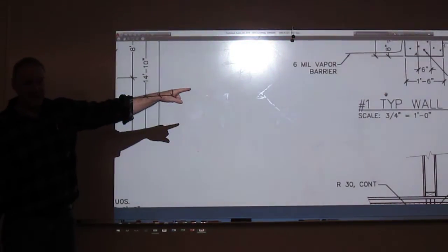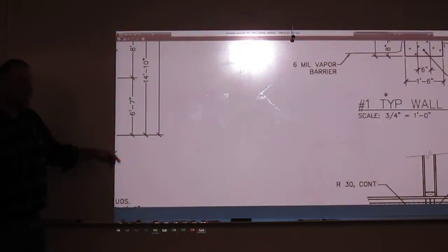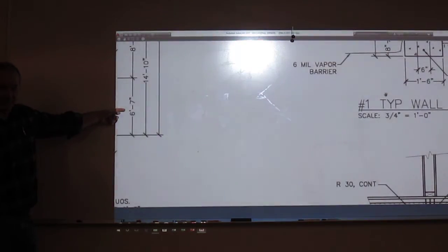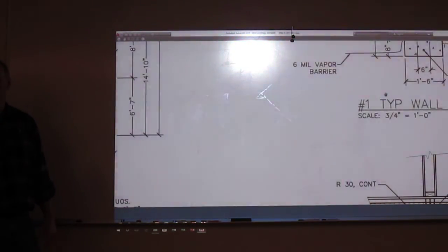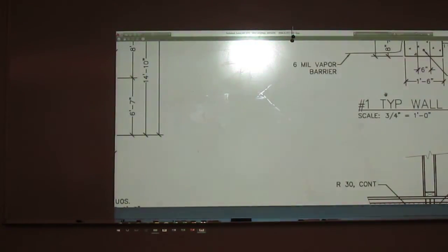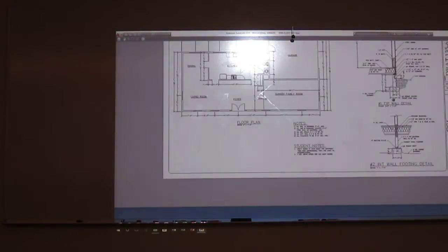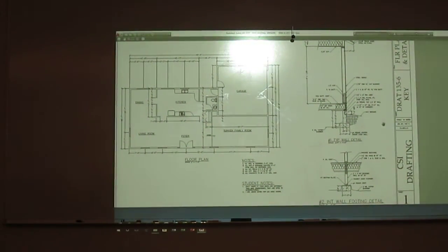Is my text an 1/8 inch high on that view? Yes. Is my text an 1/8 inch high here? Yes. Everything wants to be the same. That's following our standards. That's really the point you want to pay attention to. But that's my hope, is that we can produce this drawing in its entirety where all my dimensions are good. On all 3 views, they all read the same.